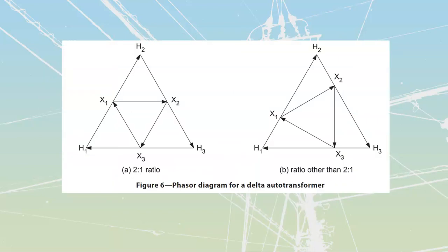They show you a little diagram just showing what the ratios are going to look like over here. The 2:1 ratio where they've got it connected directly across the high voltage to the secondary, smaller voltage, the low voltage. And then they show that as they rotate that triangle through, once again, they're going to be able to achieve other transformation ratios. But those other transformation ratios are always going to be limited to never more than a 2:1 type of transformation.